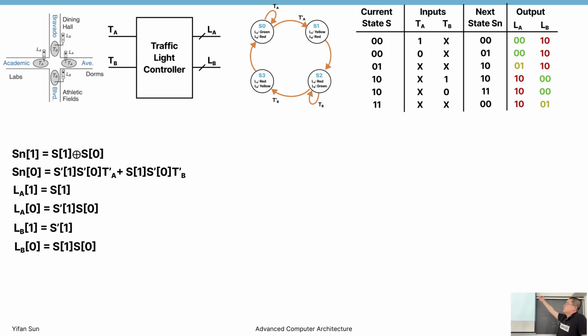We convert these symbols of state into binary representations of this state, state transition, right? Then using this state transition with 4 input and 4 output, 4 input and 6 output, we can generate equations. We can generate 4 Boolean expressions that describe what our circuit will be if we want to design a logic like this. So once you have this expression, then it's not hard to draw a circuit. So let's draw this circuit together.